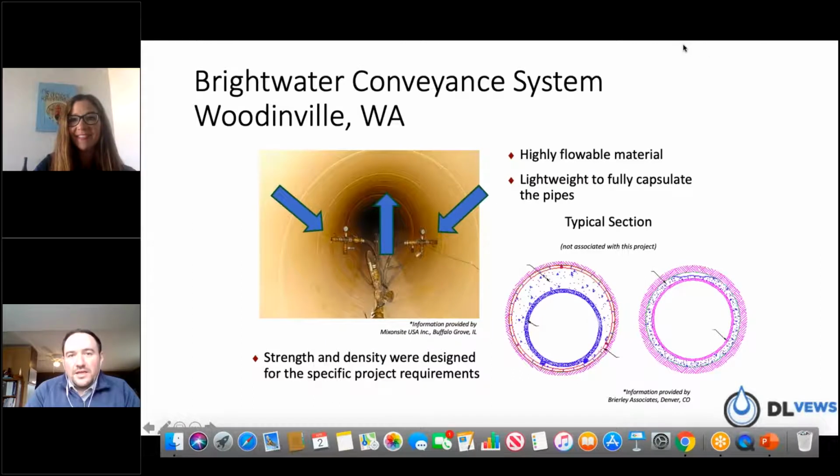Absolutely. In short, grout ports do a number of things for you, in my opinion. One, it gives you more ability, more viewing points. If you're installing a 1,000-foot run and you have access to that liner, the grout ports allow you the ability to view how the grout's doing. Obviously, if it's a smaller diameter pipe and you're not going to get in that pipe, grout ports are essentially a moot point. There's no sense in using them.